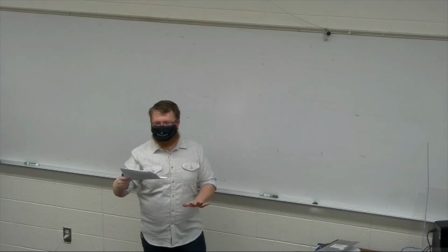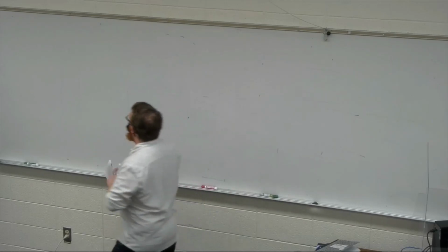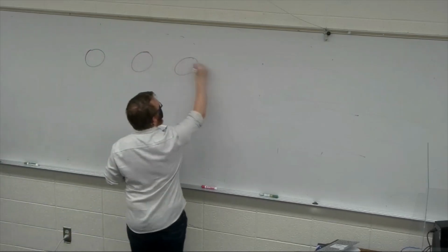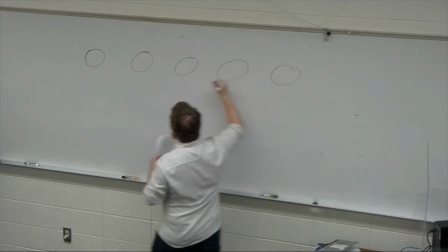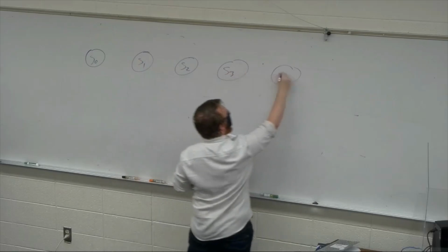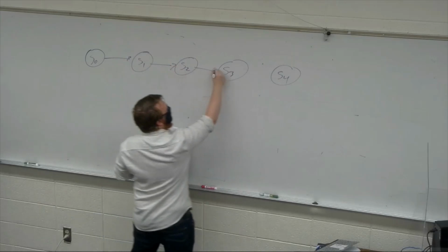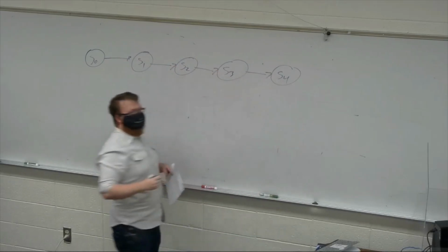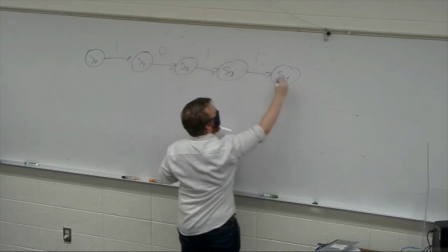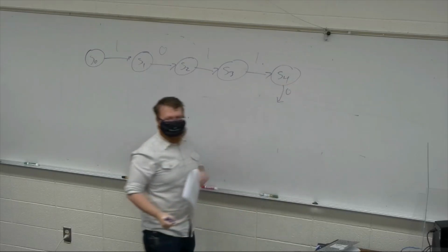There should be 5 states. So just a quick tip, if you ever have to draw these things, the nice brute force way to do this is start by drawing the detection sequence, right? 1, 0, 1, 1, and then we know we have to do something with 0, but we don't know what yet.